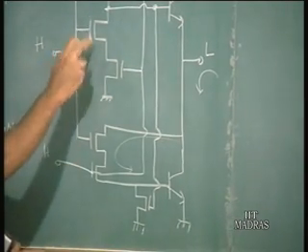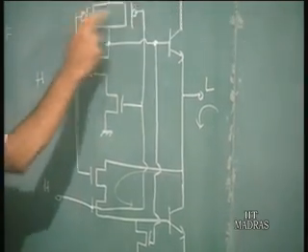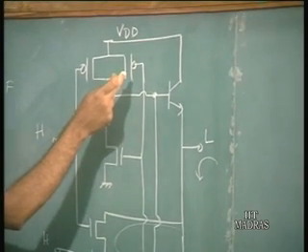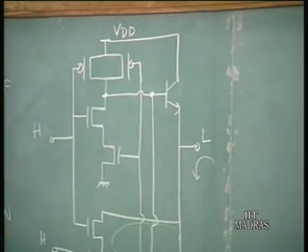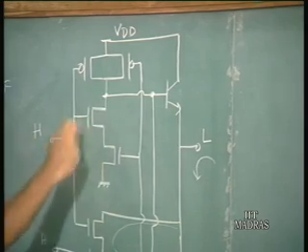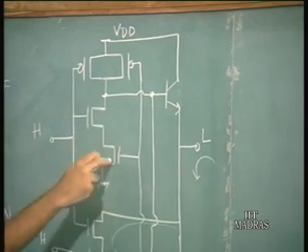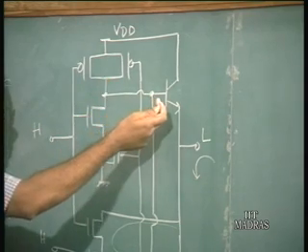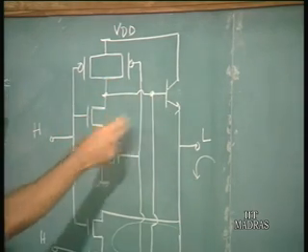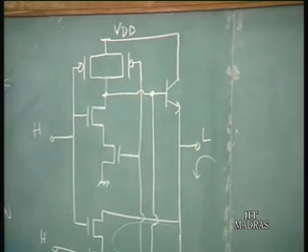And also when both these are high, then these PMOS transistors are off. Okay. So, this upper bipolar transistor is off, whereas these two transistors are also on. Okay. These two NMOS are on, which enables the discharge of whatever base charge is in the upper transistor.